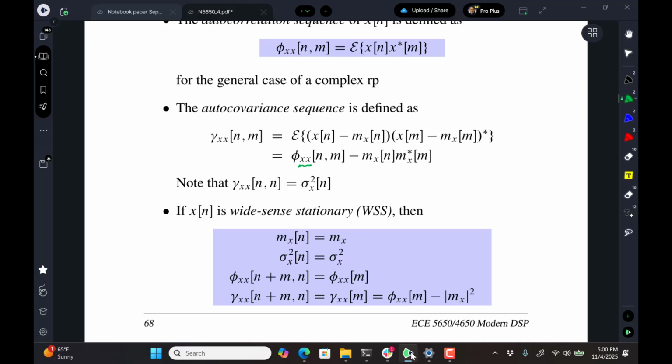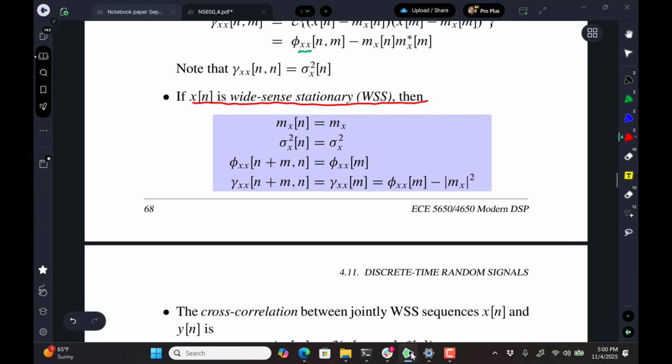So the first set of assumptions that is going to make life simpler is wide sense stationary. Like I was saying, if x of n is assumed to be wide sense stationary, then we have this nice simplifying assumption. It doesn't matter absolutely where the slices are taken in the joint moments that we're forming, x at n and x at m. All that matters is the separation. So if I move along and keep the separation the same, the statistics don't change.